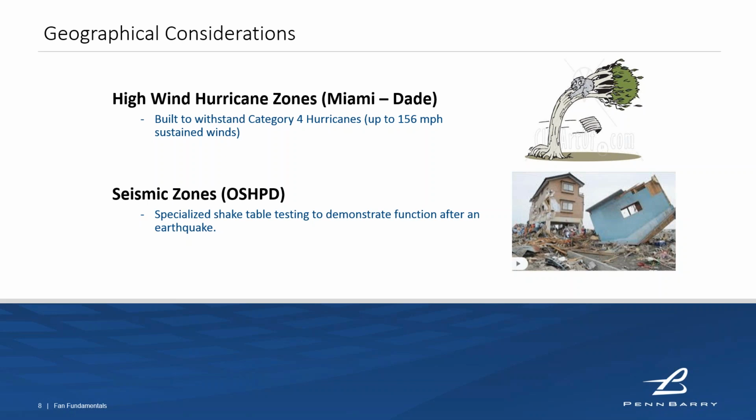It has become universally accepted as the standard for seismic activity ratings. So it's a very expensive, very involved process. To boil it down, effectively you have to build your equipment, put it onto a shake table, shake it, and then demonstrate that it runs. Again, no real quantitative answer on how long does it run, how well does it run. It just needs to start and run.